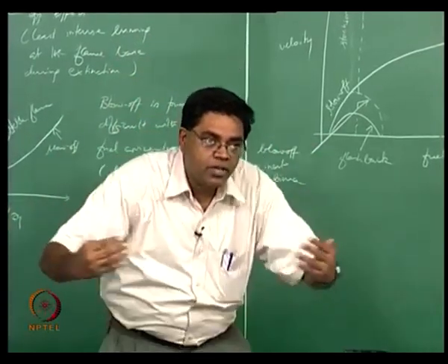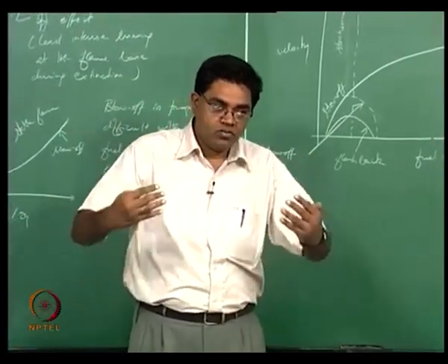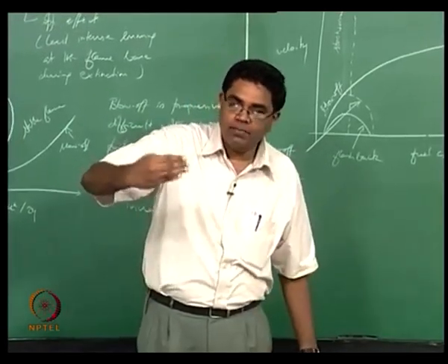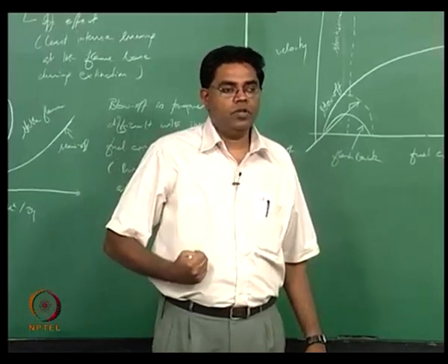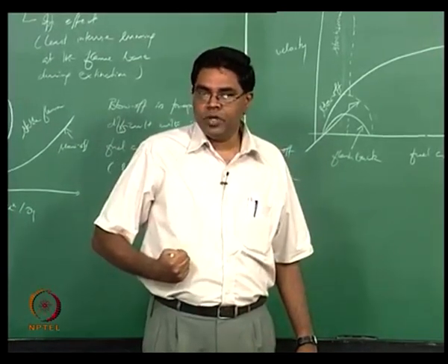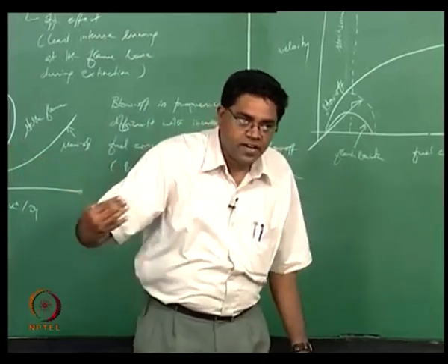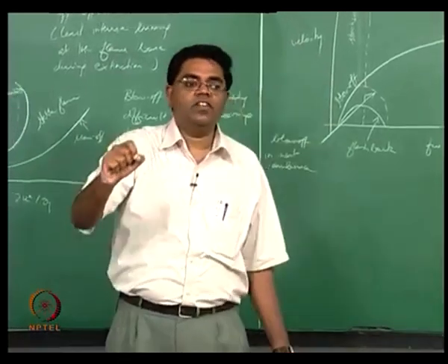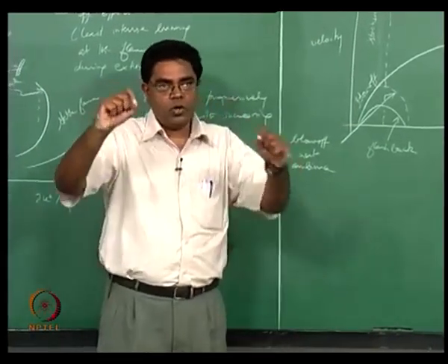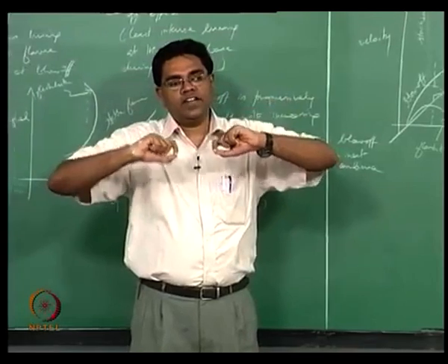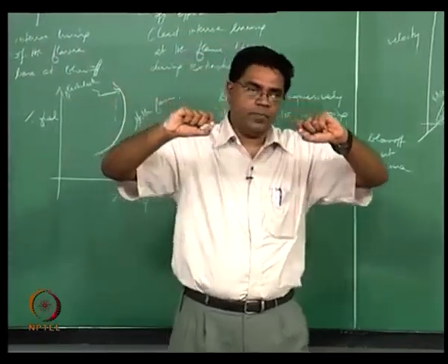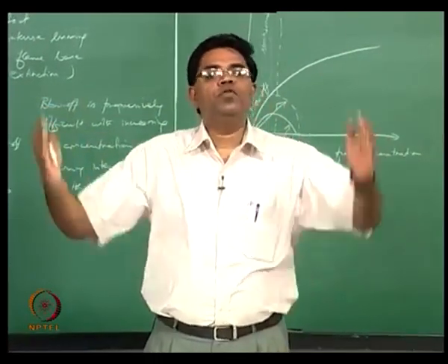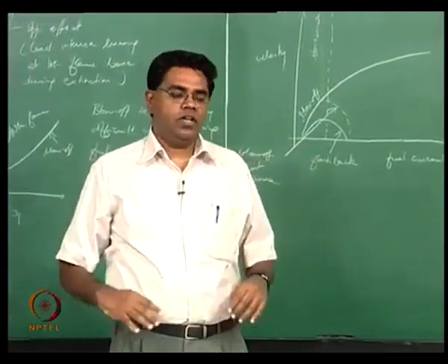They are still going to have some fuel that is remaining which can mix with the air downstream of the flame, not only at the base, not only through the gap between the base and the burner rim. What we have been talking about is this mixing effect that's happening between the flame base and the rim, so as to focus on the flame stabilization. But on the whole you are going to have an excess fuel that's coming out of the flame which would mix with the ambient and form a diffusion flame envelope that's around the premix flame.